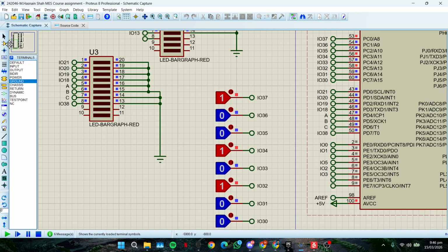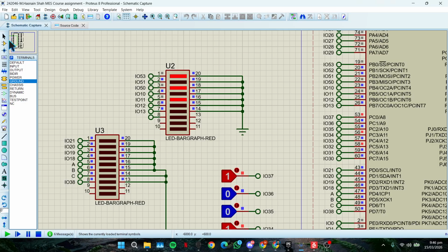So what's happening over here? You see the port B bar graph. This is our port B bar graph, and it has lit up. The microcontroller sees that 41 is less than 100 and routes the digital signal accordingly. Port D remains completely dark. So here port B lights up and D remains completely dark.